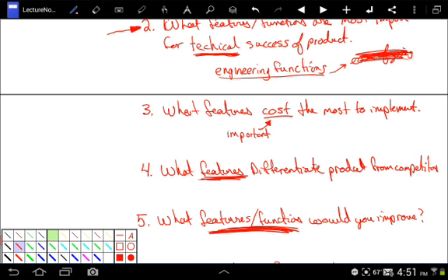So what's the advantage of using just centrifugal force to force particles out of airflow? One, you don't need fiber filters, right? So what are your maintenance costs? Or, not maintenance costs, what would you call that? Probably maintenance costs. What are your ongoing costs with a centrifugal particle filter? They're very low, right? Very low. So that's something that differentiates you from something like a fiber filter, right? A fiber filter, every time it fills up, you have to go in there, you have to stop your process, you have to replace it. It's expensive.